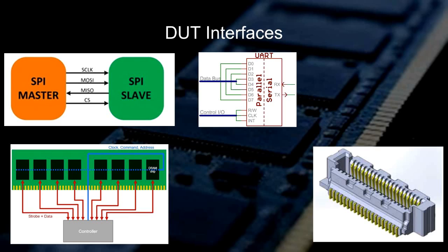All communication will pass through the Samtec high-speed board-to-board socket. While seemingly not a viable option earlier on, sourcing and design constraints lent to the daughter card route becoming more of a challenge that could be undertaken. With the Samtec parts, high-speed and promising signal integrity claims increase the viability of the daughter card option, hence why it was chosen for this design.